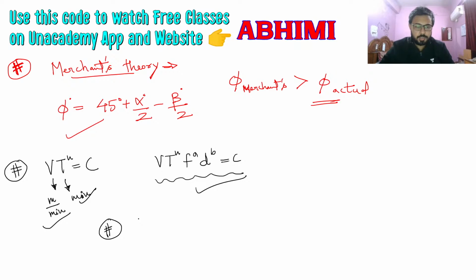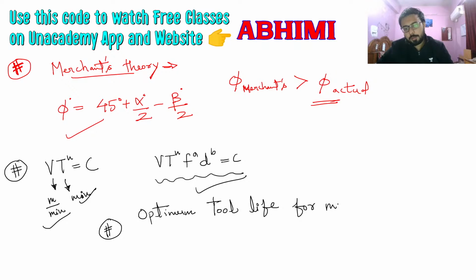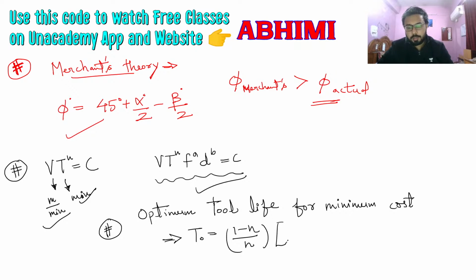let's discuss one more thing, that if optimum tool life for minimum cost is asked, then it will be T naught is equal to (1 minus n) divided by n, and inside the bracket we have Tc plus Ct divided by Cm.